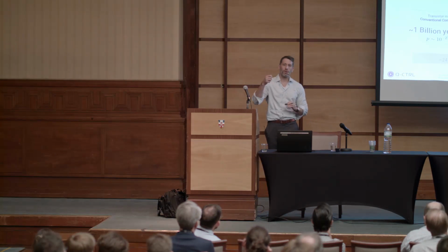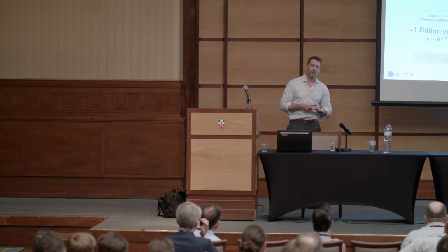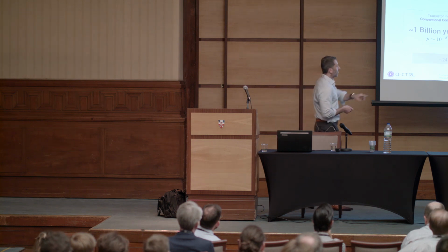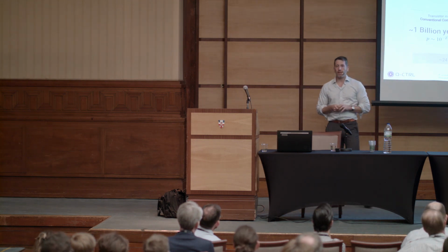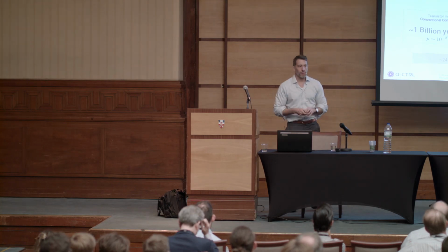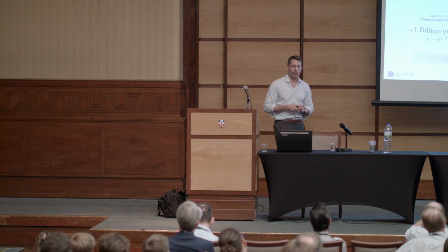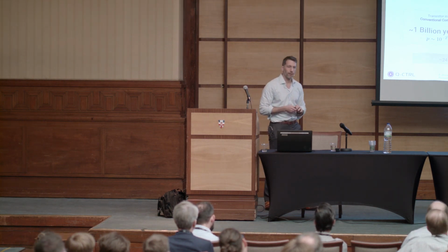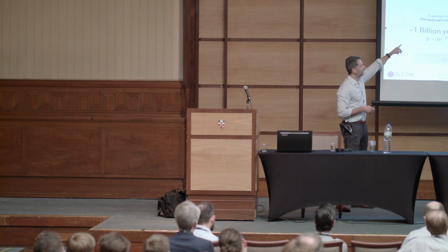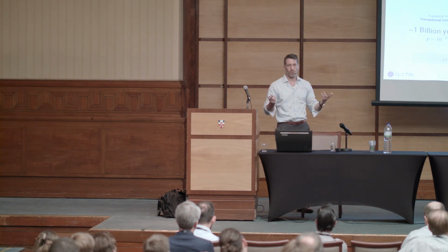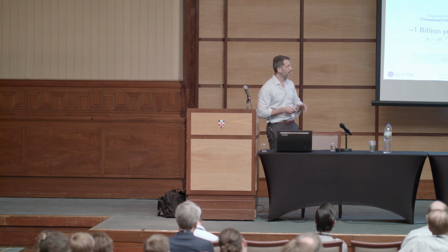Failures in time are the number of failures in a billion hours of continuous operation, right? And so the numbers turn out that the probability of failure of an individual kind of logic gate, one operation occurring in a clock cycle on a single transistor, is something like 10 to the minus 24 to 10 to the minus 27, right? And so that means that a single transistor in your computer can run for about 1 billion years continuously at a gigahertz before it's likely to suffer a hardware fault.